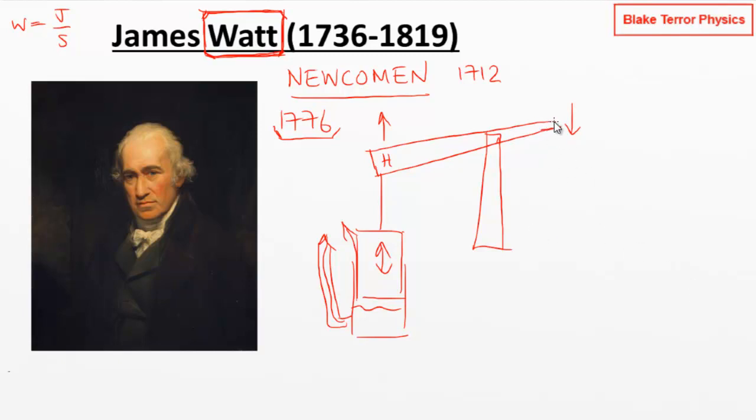So this is great. Let's have a closer look at what's going on at this right hand end then with the Newcomen engine. Right, so we attach this to a piston. So we've got a plunger going into a sealed column. So this is all sealed off. And we've got some space at the bottom here of the piston when the plunger is sitting at the top in this equilibrium position. So we need to get this plunger to go down into the piston, which will pull down the right end, pull up the left end, and allow us to start pumping stuff over here. So how are we going to get this piston to go downwards?